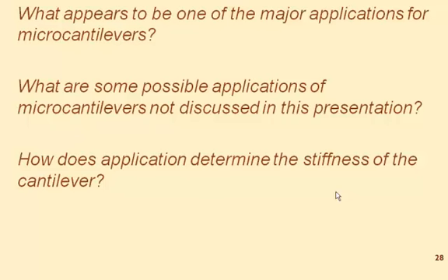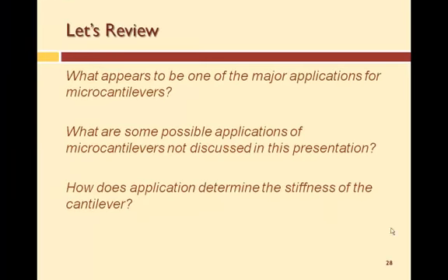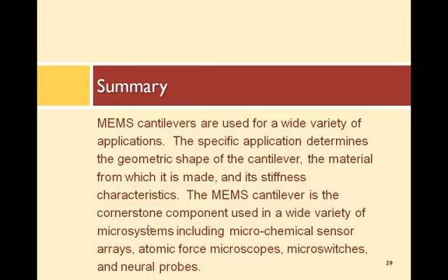So you might have to adjust the stiffness. And there's different ways to do that. You might also want to change the stiffness to adjust the frequency it runs at, because your off-the-shelf electronics run at a certain frequency, right? So if you make it too stiff, then now you're going to have to build new electronics to run that sensor. So you have to think about, okay, what's this sensor going to hook into?